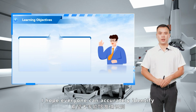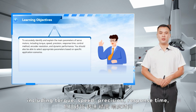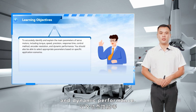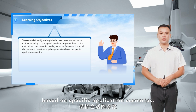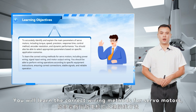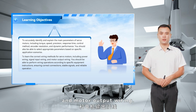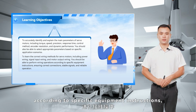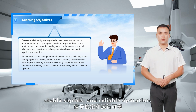Through this lesson, I hope everyone can accurately identify and explain the main parameters of servo motors, including torque, speed, precision, response time, control method, encoder resolution, and dynamic performance. You should also be able to select appropriate parameters based on specific application scenarios. You will learn the correct wiring methods for servo motors, including power wiring, signal input wiring, and motor output wiring. You should be able to perform wiring operations according to specific equipment instructions, ensuring correct connections, stable signals, and reliable operation.